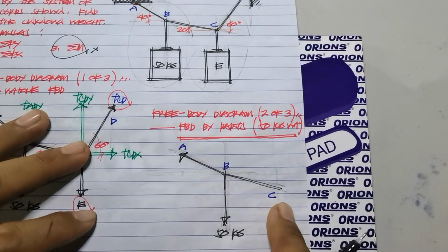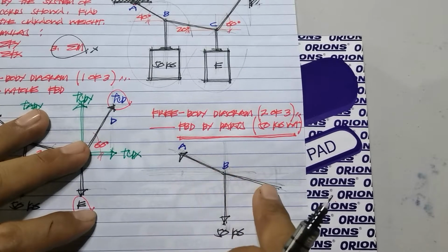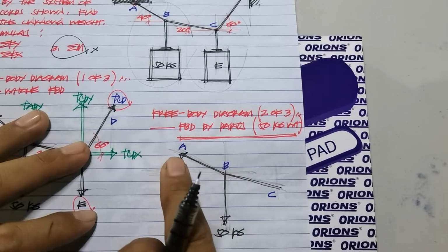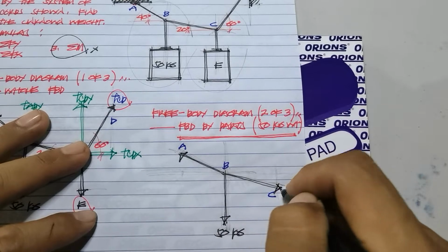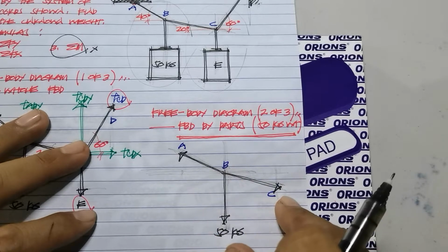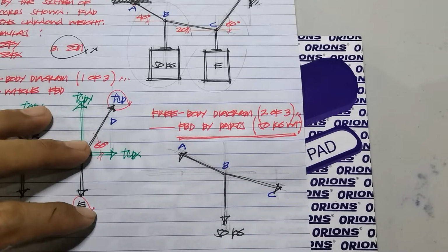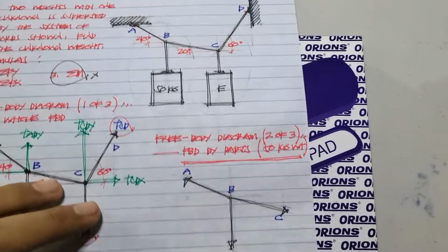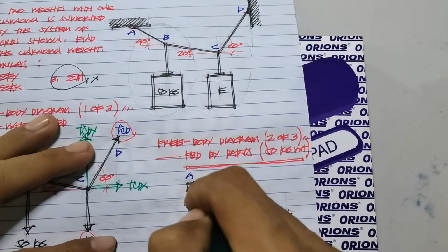So for TBC, it cannot be directly going up, because the tendency is that the whole system of forces would not be pulled. In that case, there must be tension on the part of AB and on the part of BC. So with that being said, instead of going up, our tension on the part of chord BC is going down. If you'll notice, we have inclined forces via tension. So once again, we break it down into its X and Y components of a force.